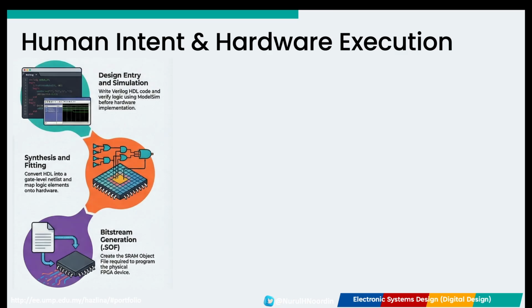In another perspective, the logic design flow is a critical process that bridges the gap between software-like code and actual physical hardware. It starts with your RTL code. The synthesis tool first parses the Verilog to check for syntax errors and builds an internal representation. It then optimizes the design, performs technology mapping to map the abstract logic directly to FPGA primitives, and generates a gate-level netlist. Finally, the implementation stage fits, places, and routes these components on the silicon chip, leading to the generation of the final programming file.